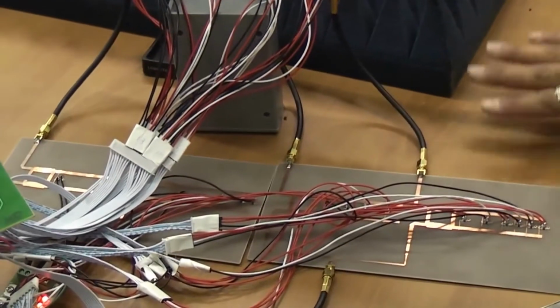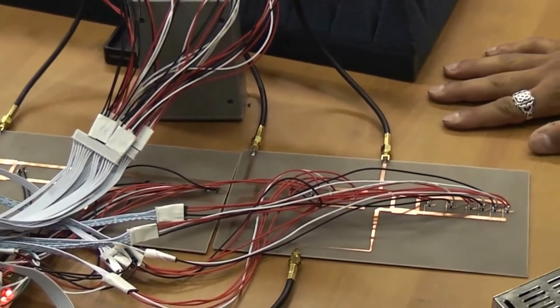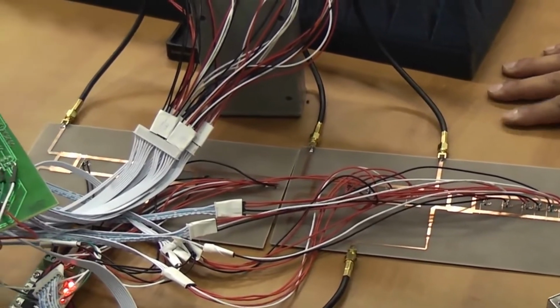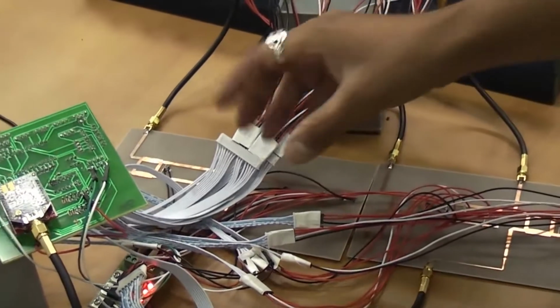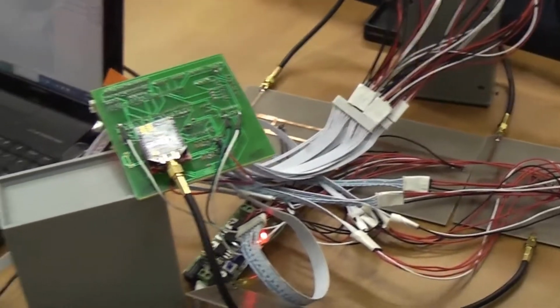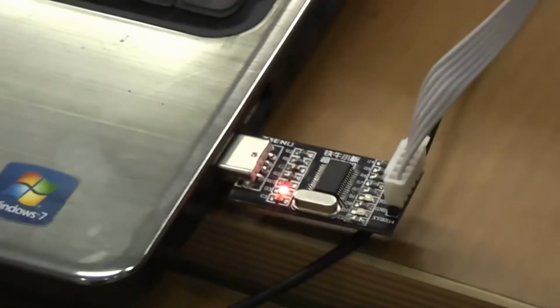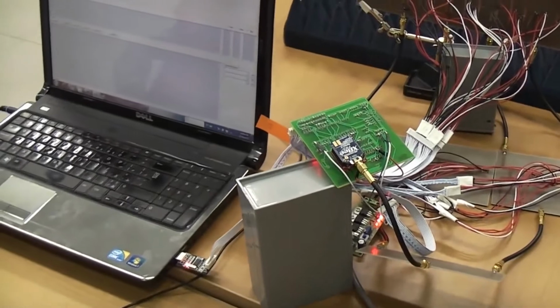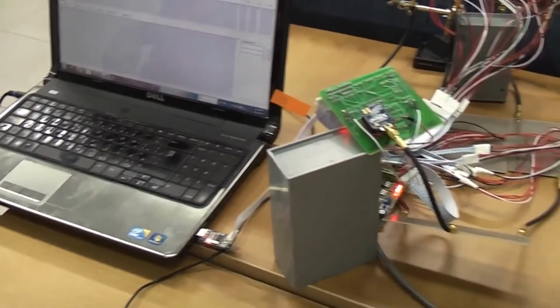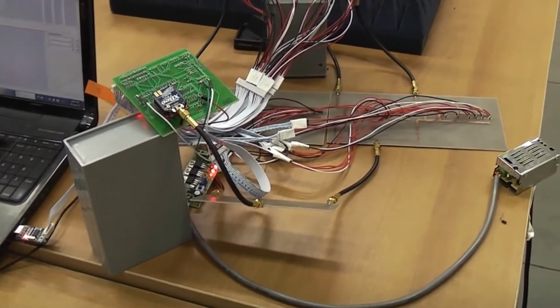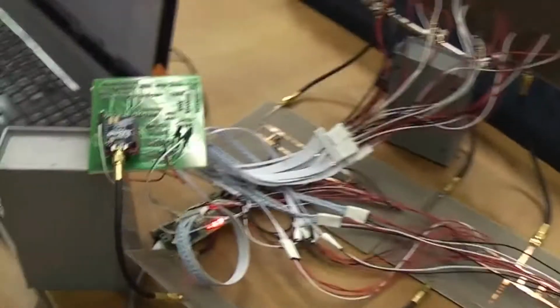We have 2 different types of phase shifters that are using the idea of reversed coupled phase shifters. Actually, they are operated with the same RF switches that we have mentioned earlier. These switches' schematics, as we can see here, are also connected to our microcontroller. Here we can see the ZigBee chip, the same as the one we're using there, acquiring the same power, and also fed through a USB or a different external power source.